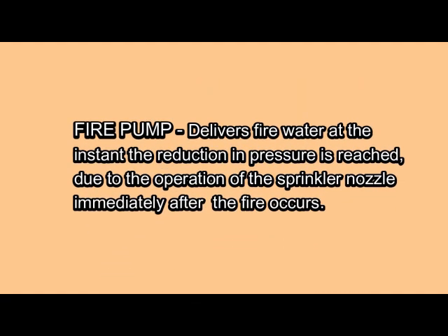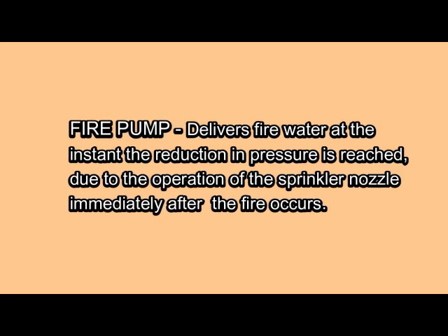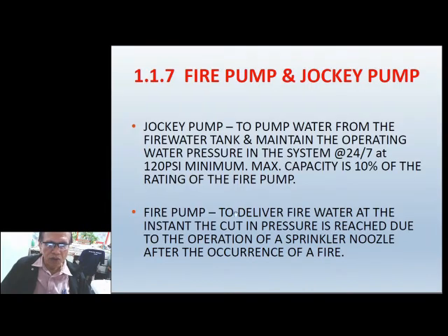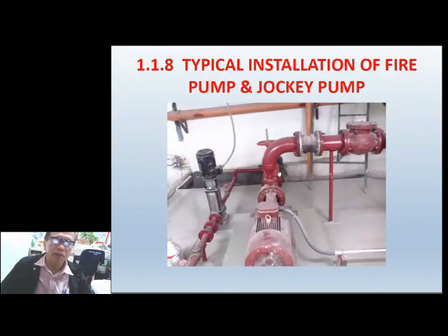Fire pump delivers fire water at the instant the reduction in pressure is reached due to the operation of the sprinkler nozzle immediately after the fire occurs. So if your fire pump is say 30 horsepower, your jockey pump can be 3 horsepower. Okay, so here is a picture of the fire pump, this one, and this is your jockey pump.